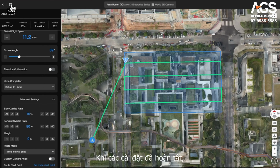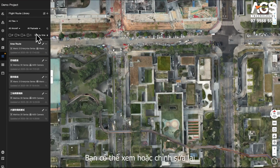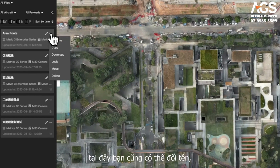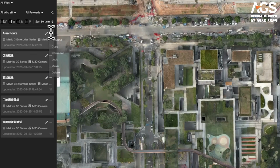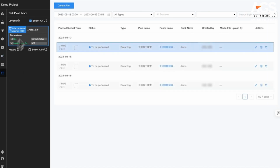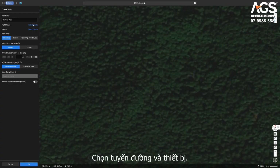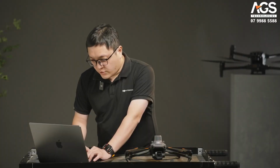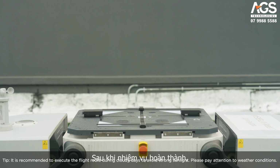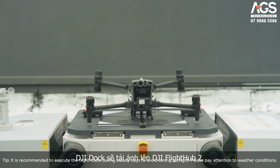Once settings are complete, save the mission. You can view or re-edit the flight route in the flight route library, which you can also rename, copy, and download the mission. If you are using DJI Dock, go to Task Plan Library, click Create Plan, and select the route and device. Based on your needs, you can choose to execute on a scheduled time or right away. After the mission is completed, DJI Dock will upload the photos to the DJI FlightHub 2.